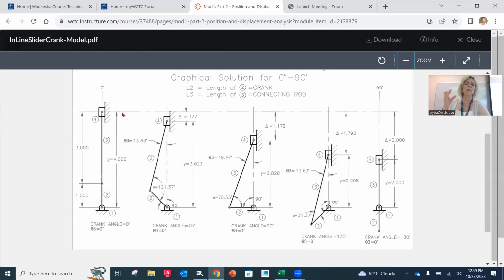Even though we might say that, if we look at the crank down here, technically it's at maybe 90 degrees from normal 0, when we determine our limiting position, we pick one of those to be crank angle 0, because that's the start of a full cycle. We're out on one end of, in this case, a stroke of the piston. So with this extended, that's going to be crank angle 0.